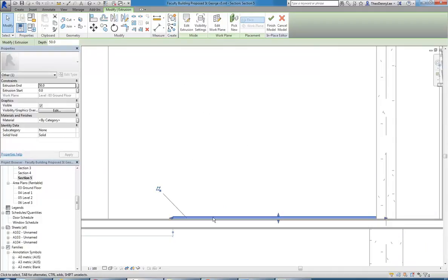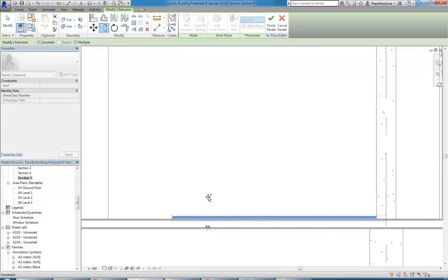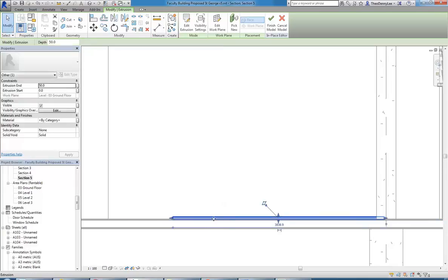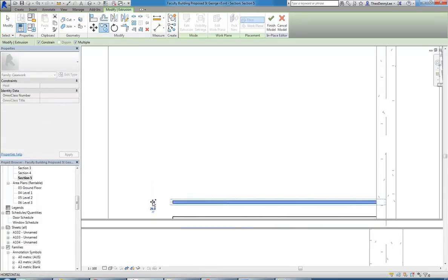And I want to copy that up, so I'm going to dissociate it, this button here. If you haven't noticed that one before, that will come up whenever you model a solid. And when that's still active, you can see there I can't lift this object away from the ground plane that I've modelled it on. But if I click on that button, diamond, that dissociates it from the work plane, and then I can copy it anywhere.